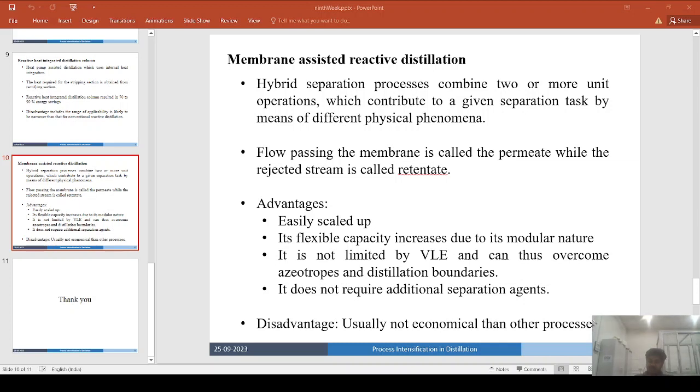And in catalytic cyclic distillation, you would get an energy savings of about 20 to 35%. And in our HIDiC systems, you would get about 50 to 90% energy savings as compared to classic processes. And in terms of reactive distillation combined with high-G distillation, it has not been recorded, but yeah, there will be no energy savings.